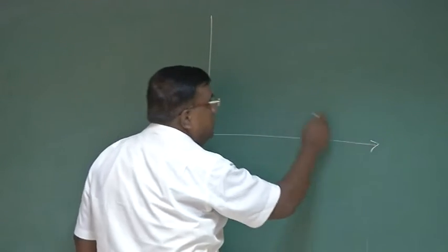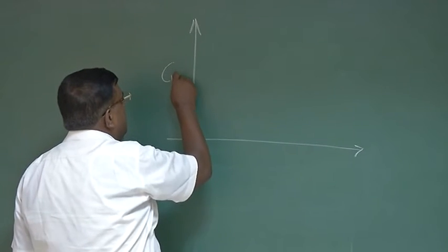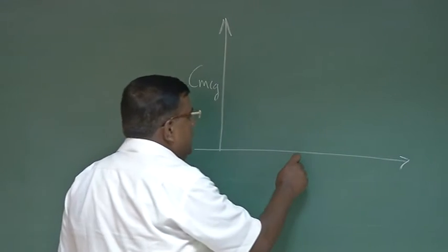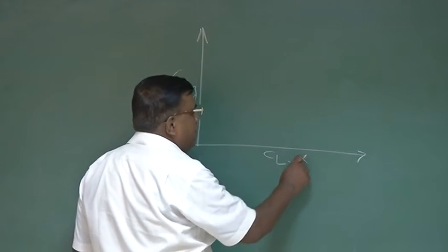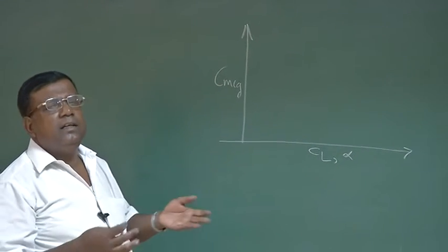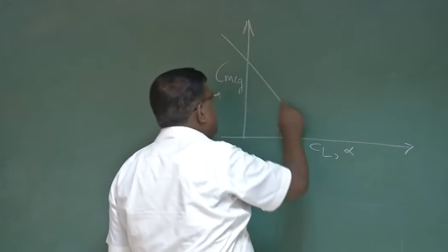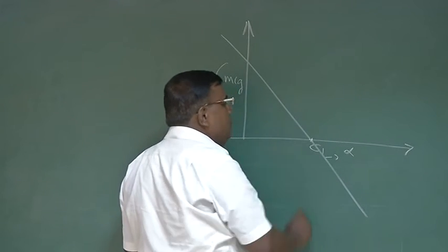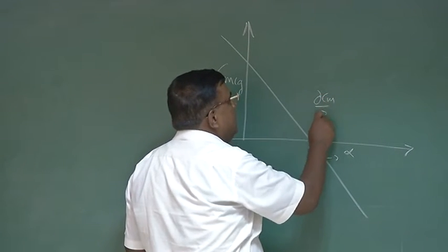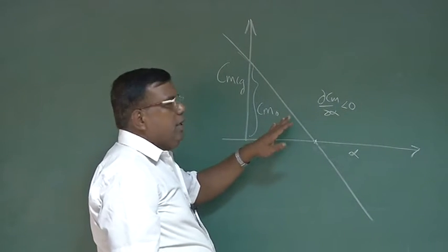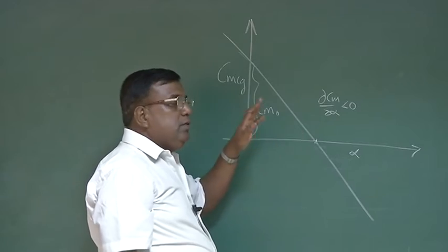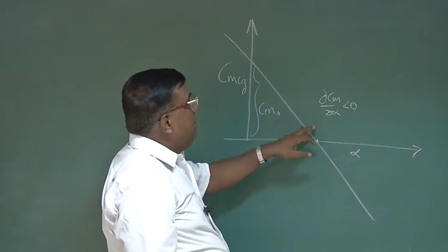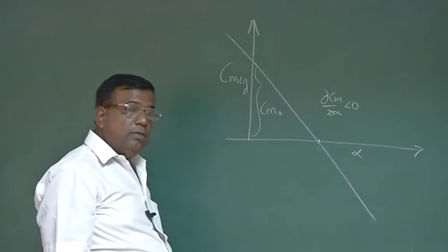That is the question. And what we learned in a nutshell was, if I am talking about longitudinal stability, that is angular motion in the vertical plane, we have seen Cm versus Cl, or Cm versus alpha. By now we know Cl and alpha are related through some scalar term. So this variation should be like this, where the slope at the equilibrium should be less than 0, or negative. This is 1. And we know that for a statically stable airplane, I need to see the slope at the equilibrium. At this point Cm is 0, and I have to check that dCm by d alpha is less than 0, so it's statically stable.